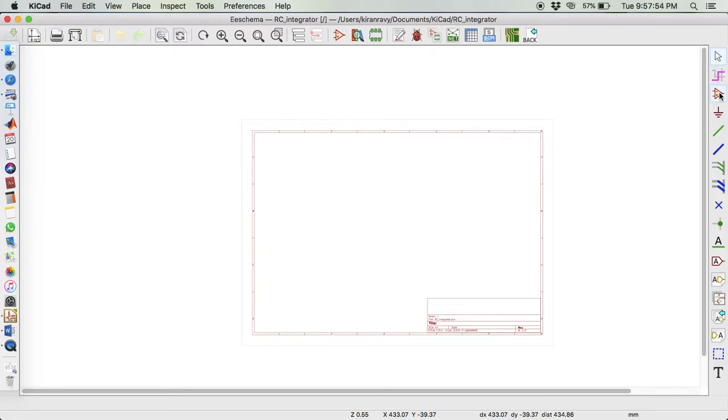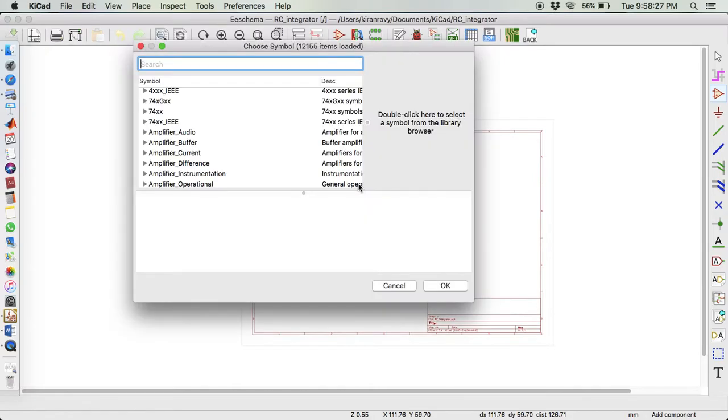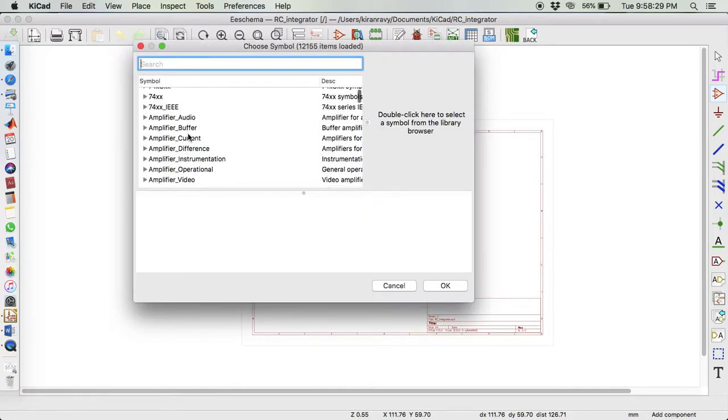So this is just an arrow. Using this you are placing the components. This is power ports, ground, as well as VCC, you will get from the wire, bus, so many things. So let's first click on this. Click on that, and then your arrow appears as a pencil here. Click on the page, so it loads a library, and from this we are doing this SPICE simulation.